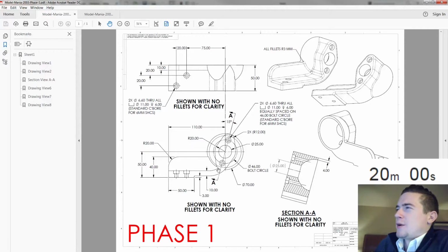So the challenge is, how can I maybe use these same profiles, get a fully defined sketch, create some solid geometry, build it off one another? Where's my origin going to be? Do I have to create any reference geometry? Right? These are some of the things I'm trying to answer right away.